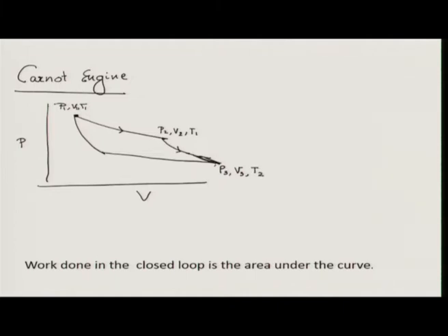This is isothermal, this is adiabatic, this is isothermal contraction bringing you to P4, V4, but since it is isothermal, it is again T2, and then this adiabatic compression brings you back to the initial point P1, V1 and T1. So, please remember this is a continuous curve. I try to make it better, well, probably better.